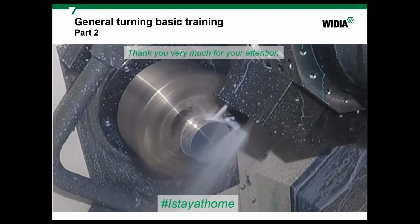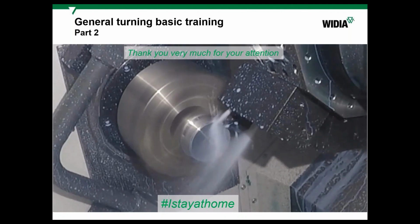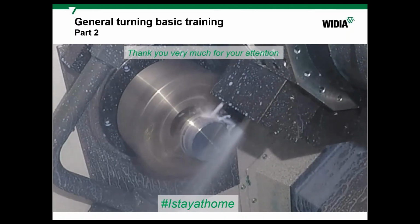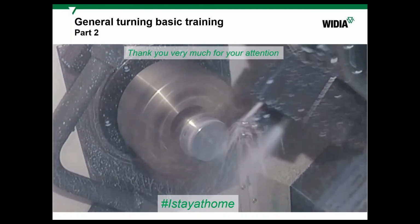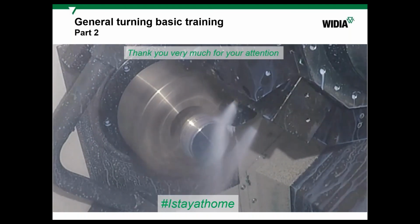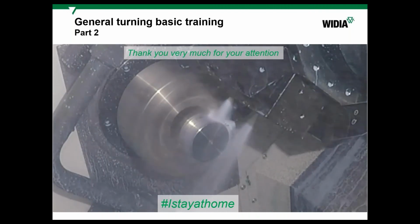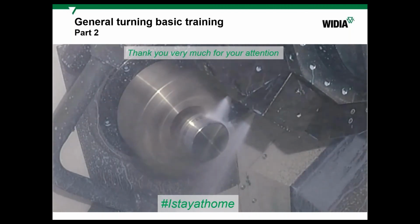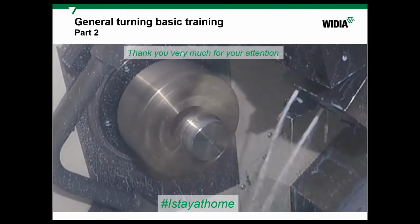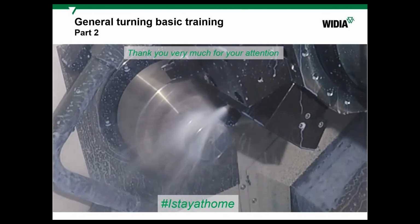Then look, if nothing happened, you can choose WP15 and also calculate the tool life. Look at the tool life and try to choose the hardest grade. Maybe not at the first, but at the second step, the optimization step, you can go to the hardest grade and get the maximum tool life, or adjust a higher cutting speed.